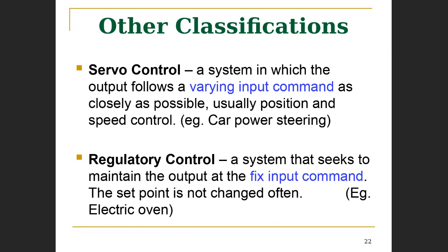If you consider your arm, each joint would consist of a motor in the case of the robot, right? To get movement, you have to be constantly changing the position of these motors to achieve the objective. We call these motors servo motors, because they're constantly receiving new or updated information as to where they need to go, to achieve the task of pick and place, all right?